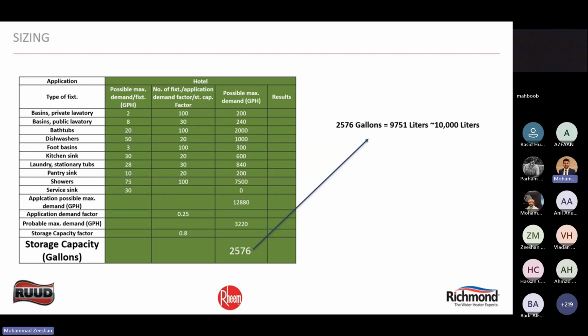It is important to have enough hot water stored to ensure that the heat pumps operate with less wear and tear. So this code basically defines peak demand in hours. We have a duty to select the recovery time, which I will take you through in the coming slides. So now we have the total demand calculated as per ASHRAE.